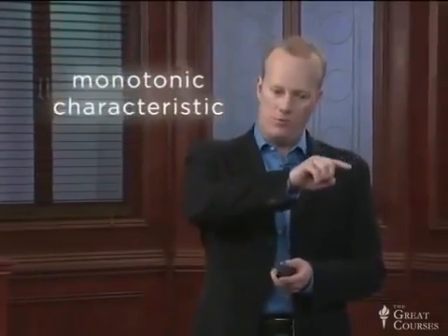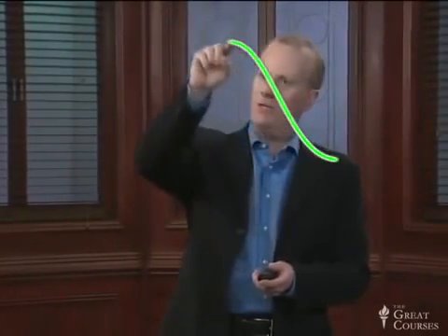This kind of behavior, instead of looking like what we call a monotonic characteristic, where for more voltage the current just keeps going up, but this kind of behavior where it goes up and then it goes down again, is a shape of what we call a transfer curve that is not currently exploited in electronics. And yet what you can do with that is you can create what's called multiple-leveled logic. You can have many bumps that you engineer through many transfer states, and you can have stable regions within them. And so you can have potentials and currents that aren't just zeros and ones, but you can have zeros and ones and twos and threes.